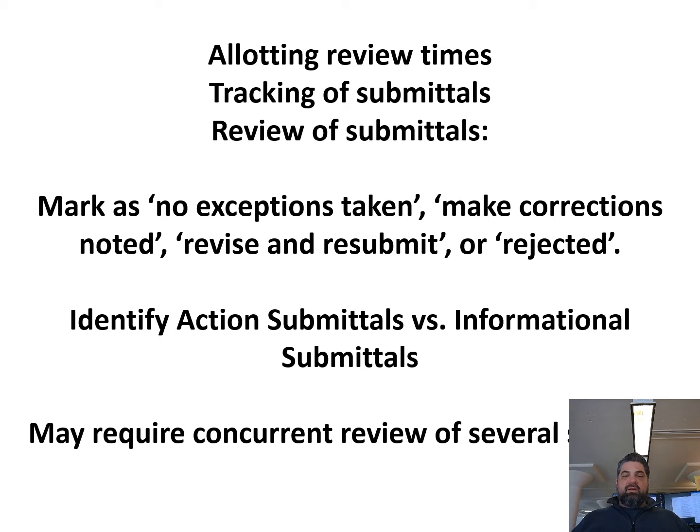They may submit something and it's like, man, there's so many things that are inconsistent with the contract documents. I really need you to revise this and resubmit it and send it back to me so that I can review it again. And so that's a revise and resubmit. But you'll want to tell them exactly what you need back, so don't make them guess. Let them know exactly what it is that you're looking for.